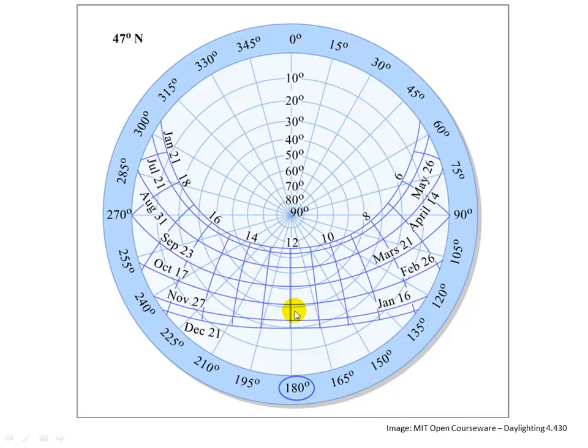And then it gets kind of shallow and low, and then it gets kind of sharp and high during the year, and it kind of oscillates between those, and you get these kind of sun charts. And what's useful about this is that if we have these angles and we know where the sun's going to set, we know where the sun's going to rise, we know where the sun's going to be, we can essentially draw this curve in 3 dimensions. And then we can input where the sun is at a certain time, and that'll give us that point where the sun is. Okay.